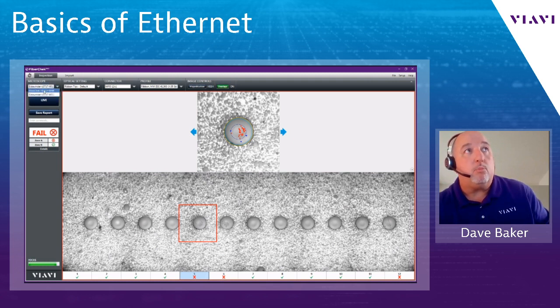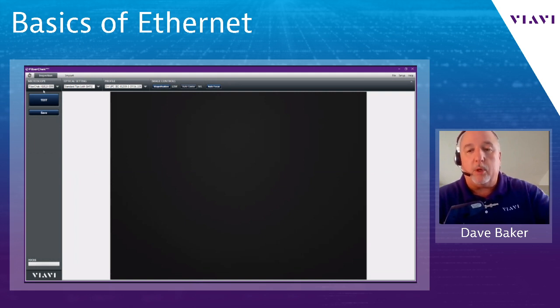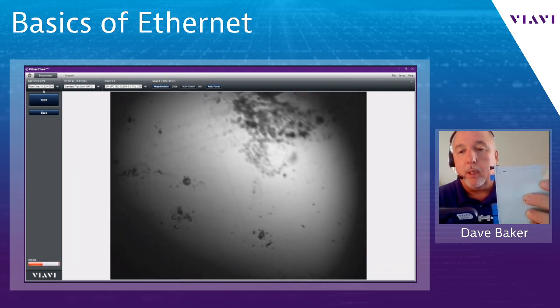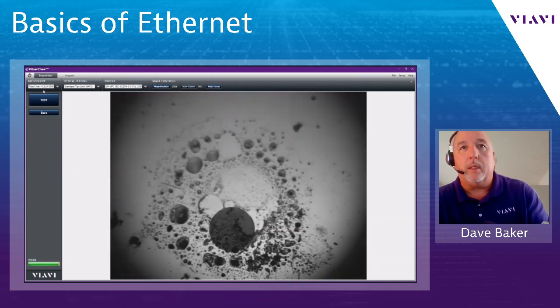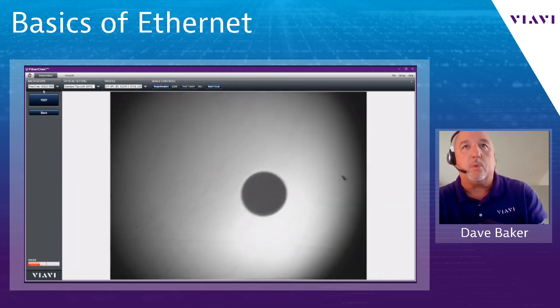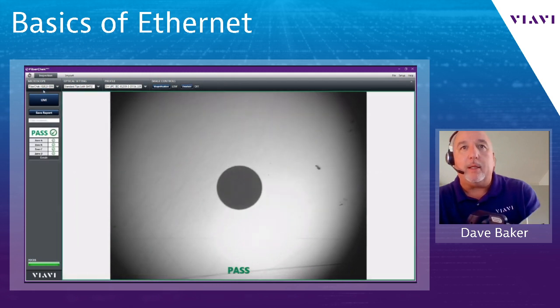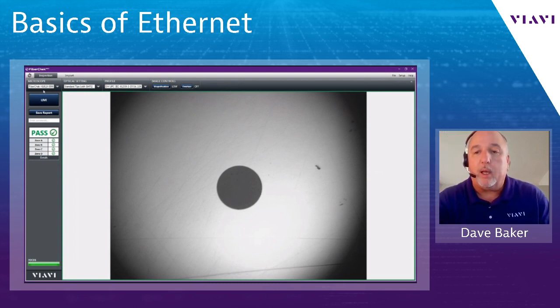I also have a regular Simplex microscope connected up here. This is a microscope just to look at single fibers, our fiber check probe. And I'll do a live demonstration of that. I have a cartridge here with some fibers in it, some bulkhead connectors with fibers in the back, and I can simply insert this into the cartridge and run a test to assess that. That's a dirty fiber. Yeah, this one's a little bit cleaner. Testing's real simple, just one pull of the trigger, and it will focus the fiber. Pull again and hold, and it'll test and give me a pass-fail analysis. So again, this is an invaluable tool in verifying whether your connection points are clean and whether you are ready to go ahead and connect a cable to it or not.